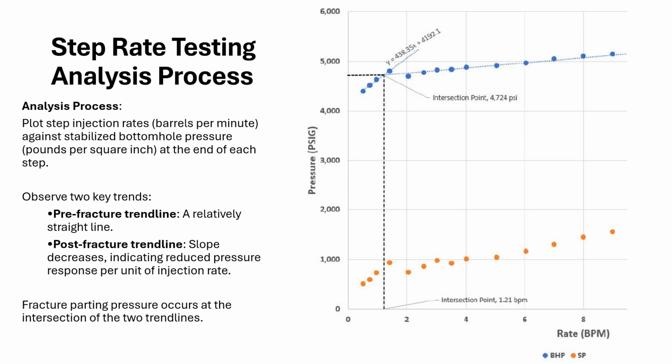Okay, thanks, Josh. The next question says, do you recommend the well be cleaned out and be sure the perfs are open to ensure you're testing the rock face and not the internal storage of pipe? Highly. I do recommend that in wells that are newly completed or in wells that have been in operation for a long time where they may have skin develop. It's highly recommended.